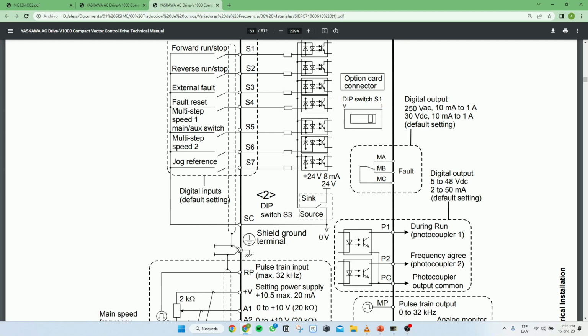Now, what is normally open is logically not going to transmit the voltage. If the coil is activated, what was set as normally closed is going to open up, and now it's going to allow the energy flow where it was normally open. Now, this is what happens with a relay.